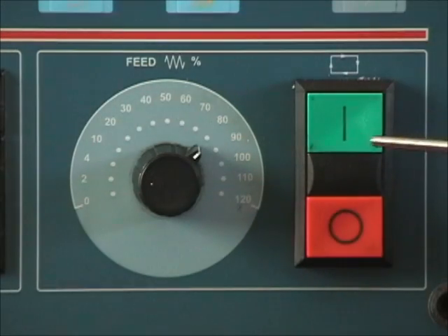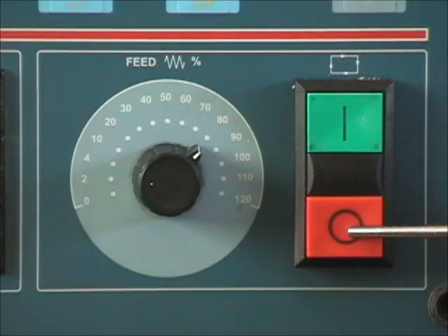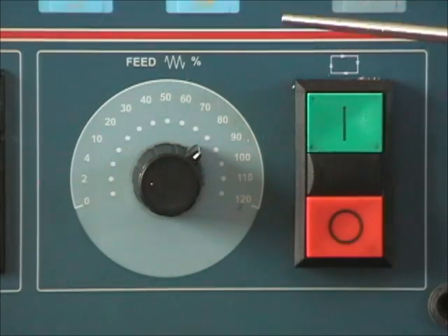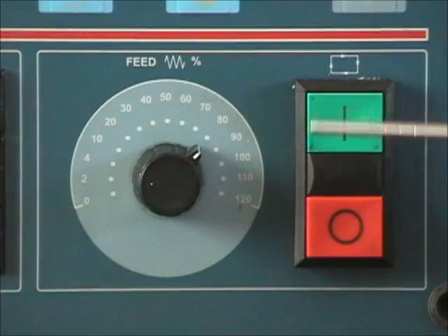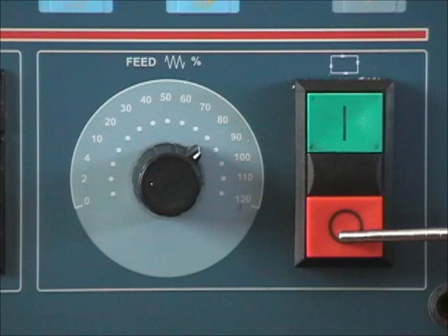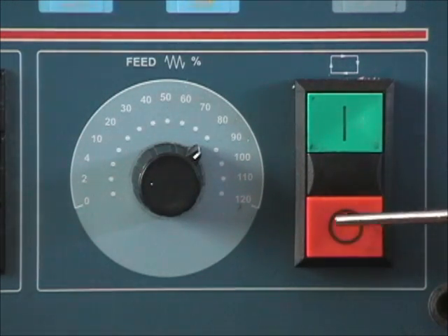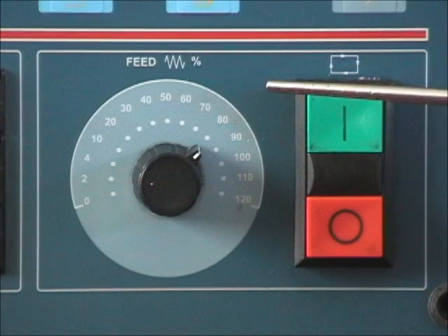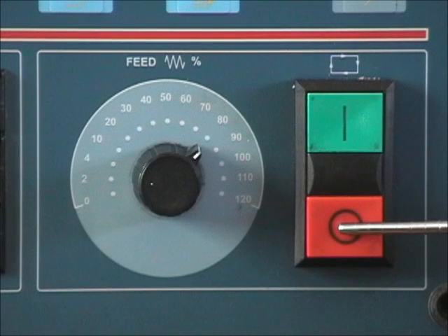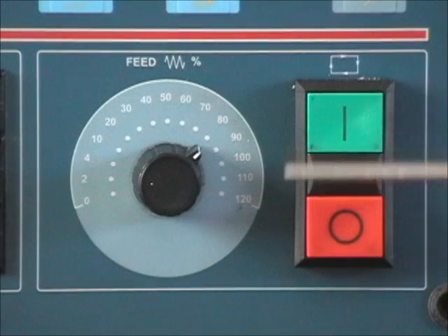Finally, area 13, the cycle start button and the feed hold button. In execute mode or MDI mode, pressing cycle start will activate the programmed command or program in memory. Feed hold will stop execution of the program and stop axis movement, but will not stop spindle speed or coolant. To restart the program, you can press cycle start again, or to reset and stop the machine entirely, press feed hold and then press the reset button just above.